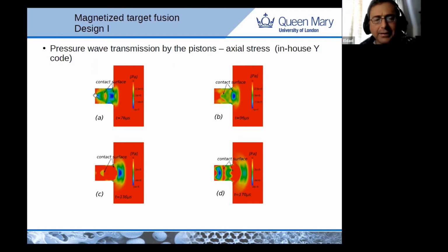So we have the hammer hitting the anvil, and we get the acoustic pulse going inside, but there is also something coming back. That something coming back can cause a problem, because, as we will see a bit later, we will have cavitation, particularly if we have quite large pressure waves leaving the anvil. And that cavitation, these bubbles can collapse and cause damage to the face of the anvil, on the side of the liner I'm talking about.